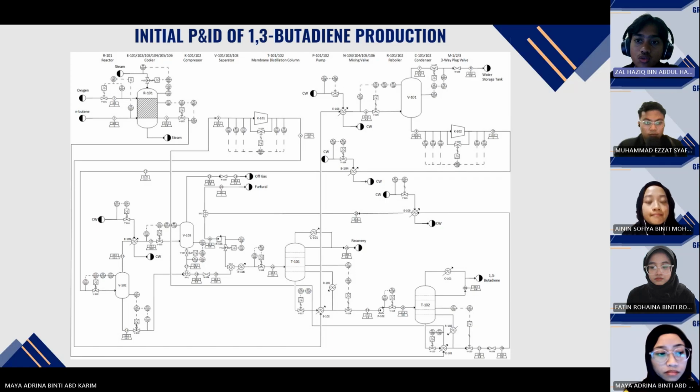The substances used and produced from this process have been identified as hazardous materials that can affect society and the environment. Butene is highly flammable and can form explosive mixtures with air. It is also a gas under pressure and can explode if heated. Additionally, it can contribute to air pollution by participating in photochemical reactions leading to the formation of ground-level ozone.